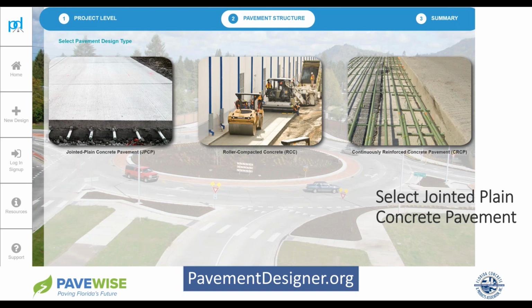Normally the DOT and most folks in Florida here use the jointed plain concrete pavement design. We do have some roller compacted concrete in intermodal facilities around the state. And we do have one example of a continuously reinforced concrete pavement that the DOT constructed in a rest area on I-75. But the choice that's normally used is jointed plain concrete pavement.